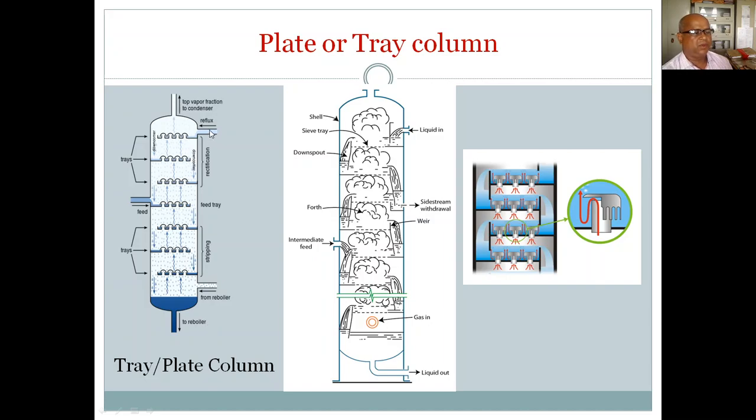And what we told, that reflux is given, it is part of your top product, to the top tray. In the tray a liquid is filled, and these are the holes here, gas is moving through them, and liquid is moving in this direction, then through this downcomer it comes to the next plate, where liquid moves in this direction again. It is a cross current type of liquid movement, and gas is flowing through the trays.